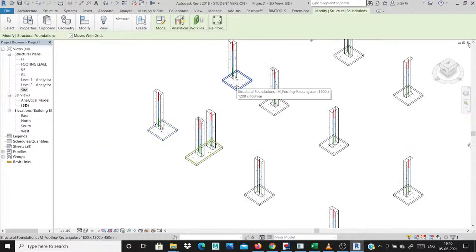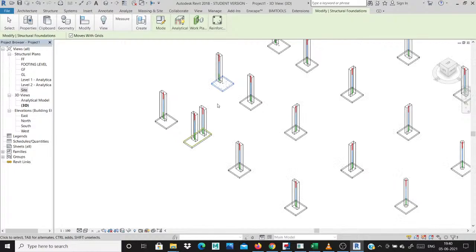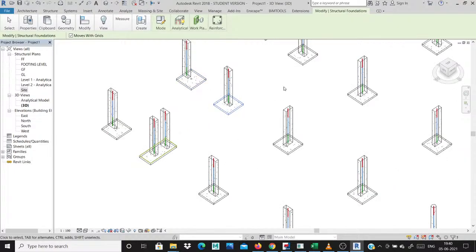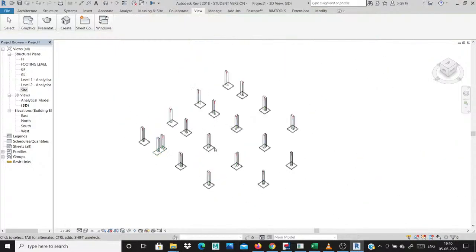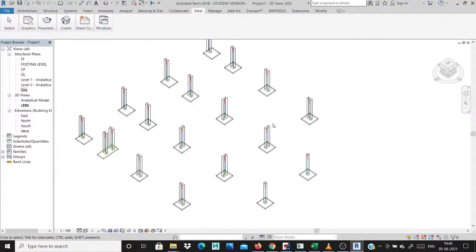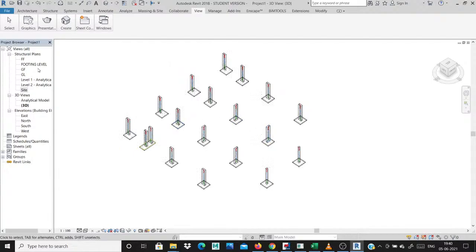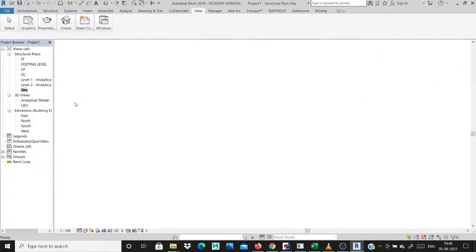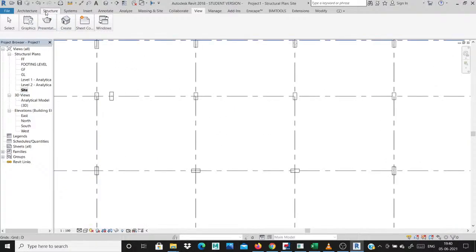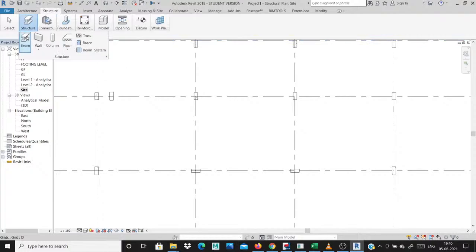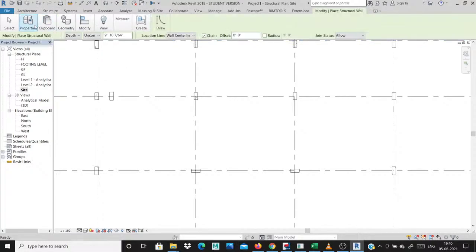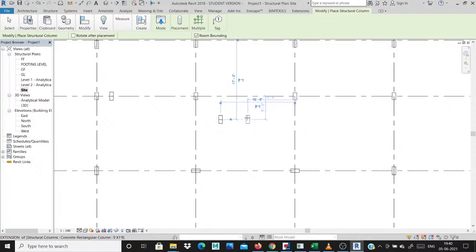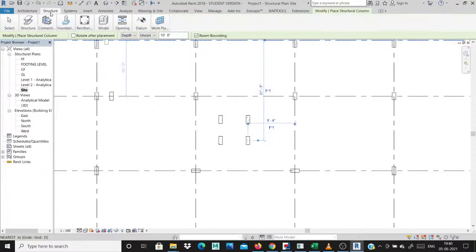See this, you simply created this eccentric footing and then the spread footing and then the normal combined footing. The same procedure, as shown in some of the buildings, for the mat footing: simply create the whole slab. See this area, I need some of the footings in this area. How to create this mat footing? Simply go to structural, structural columns. Okay, go to structural columns. See this, I simply click these four columns for my lift area. See this, four columns.